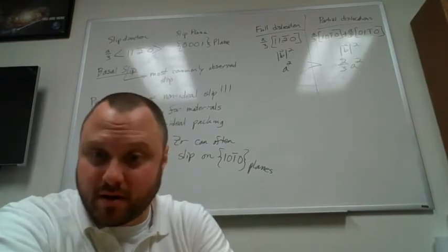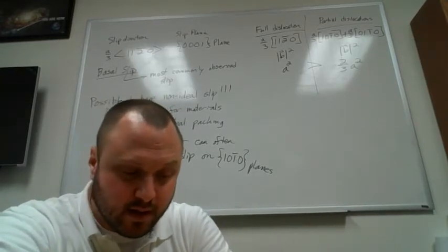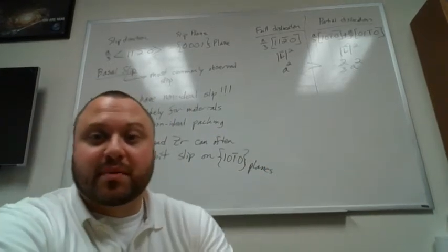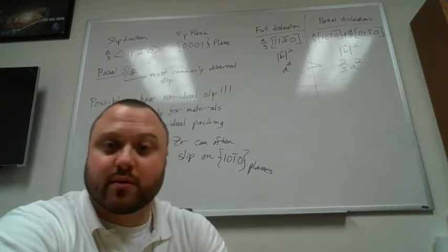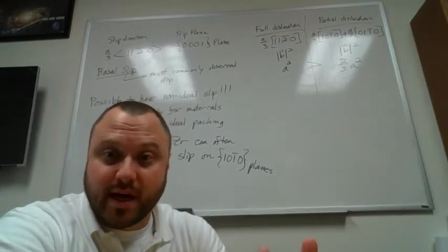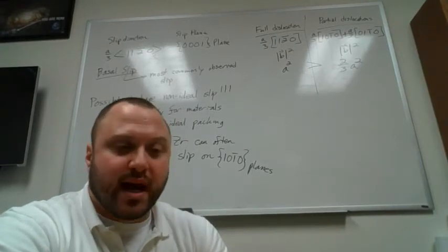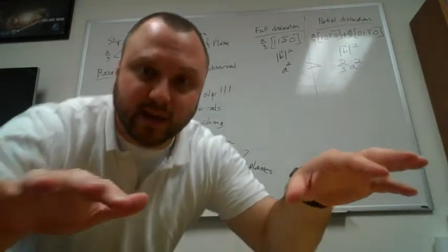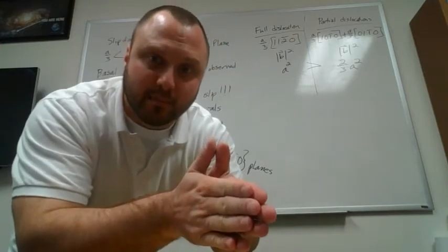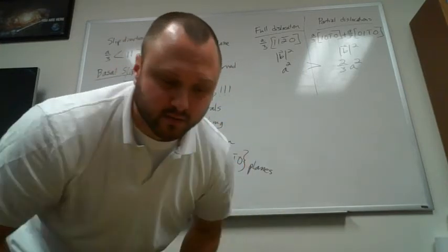We now have mixed dislocations. Okay, so if we started with an edge, we now have something with an edge plus screw character. If we started with a screw, we now have something with an edge plus screw character. And we can have all the same complications that we saw in FCC. We can have these partials gliding along planes. We can have them interacting. Sometimes they have to recombine before they can do things inside of our crystal structure.